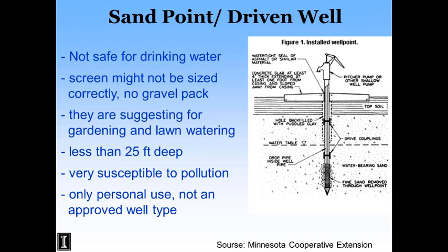This is a sand point or driven well. When you're in an area where the aquifer is close to the surface, sometimes you can push in a screen and get your water that way. There are areas all over the country where it's near a river and it's sandy where you can do this. The thing you need to remember is when you don't have much topsoil and it's sand at the surface, anything from the surface can infiltrate into the water table and eventually get in your well when you start pumping it. What we recommend to folks who have shallow sand points is use them for your garden or other things. Don't use them for your drinking water supply.